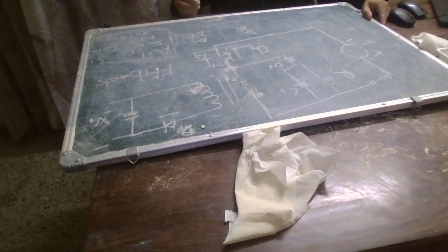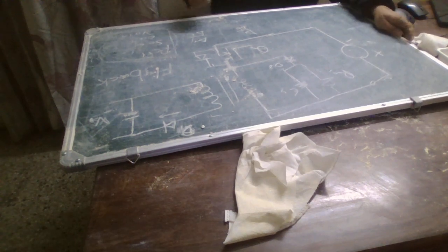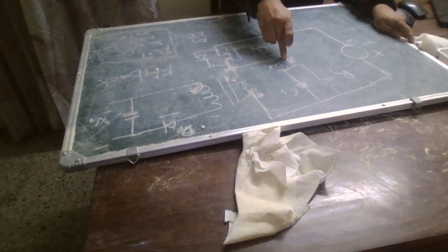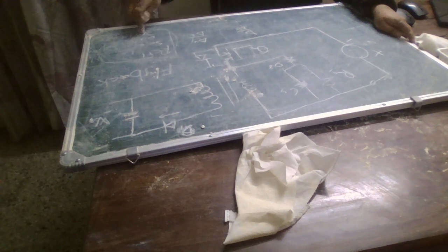It should be at this reflected secondary output voltage also, and that's the V clamp voltage and the leakage stored energy. So this capacitance will get charged as soon as the diode gets forward biased. The charging can be more than the reflected secondary voltage.